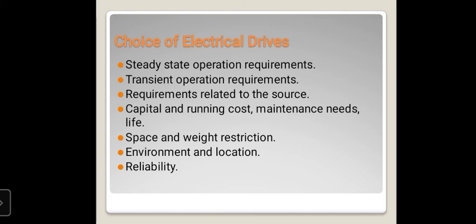So we cannot choose that kind of motor there. In case of submersible, we also have to choose a squirrel cage induction motor. So based on the environment and location, we have to choose the electrical drive system.